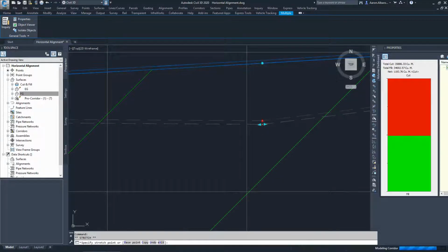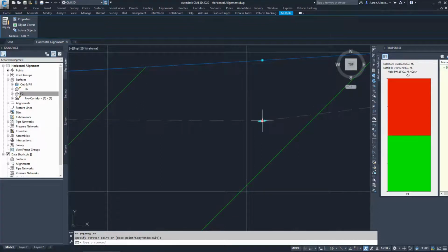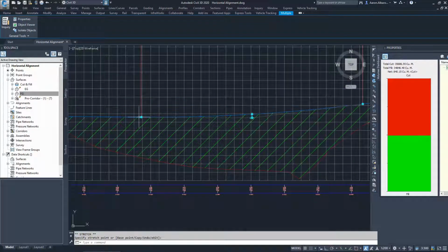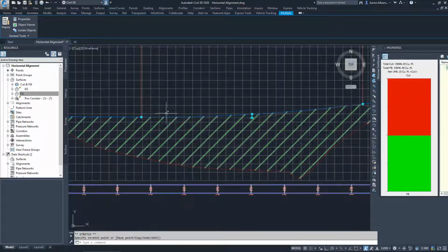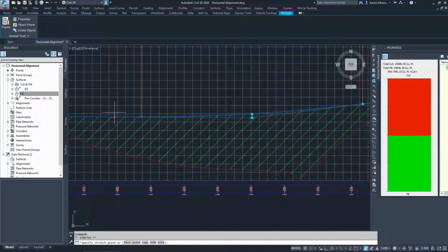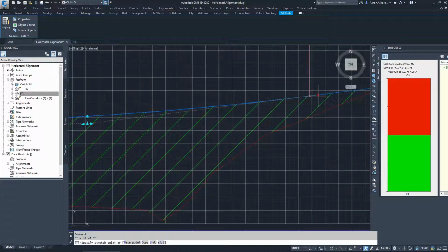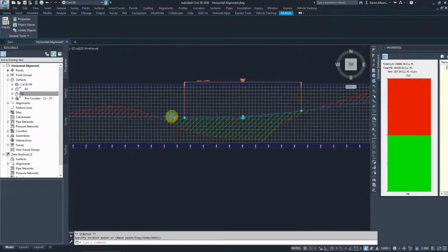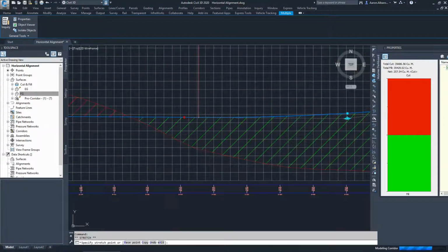So I went too much in the other direction. This minor adjustment now, I still have more area of cut, less area of fill. So if I make this slightly larger, that will make a very minor adjustment, and we are down to 408 cubic meters. That's 275, 257. We'll add a bit more, make the curve larger. That's it. We are almost near 0.